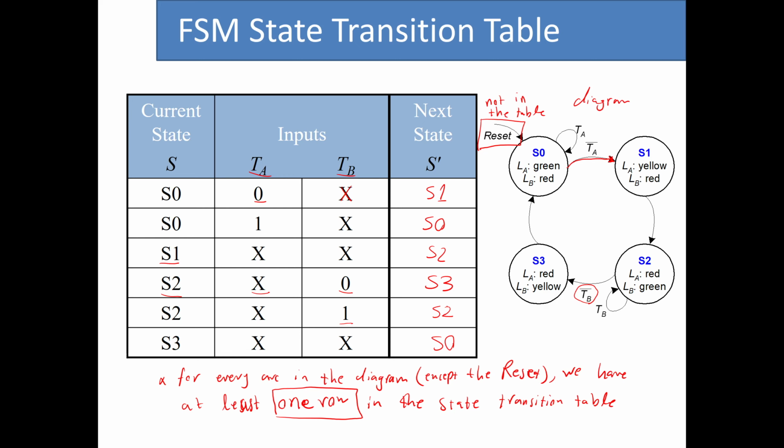So this is a very simple step to go from the state transition diagram to the state transition table. And as you will see later on, designing an FSM consists of several steps, but these steps are usually very small, so we change things incrementally, right? But you need to keep all of these steps in mind, and you cannot change the order of these steps. Otherwise, you basically end up at a dead end that you don't know how to proceed from.